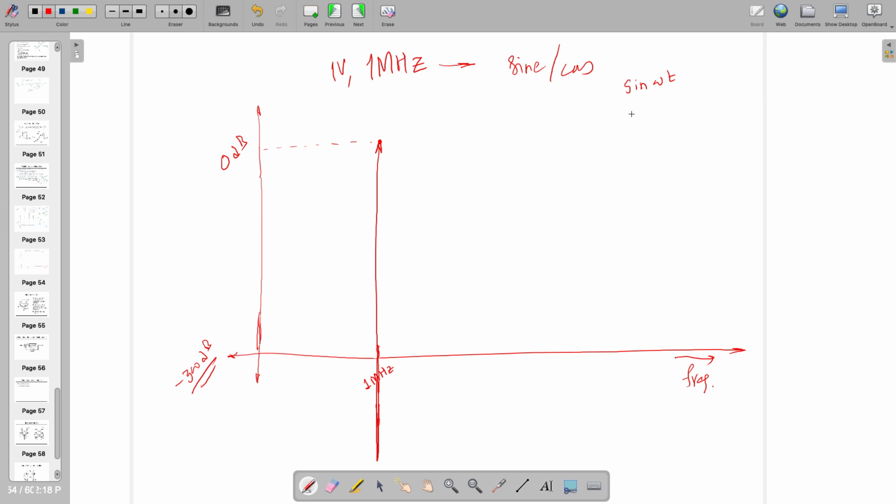No, we are not passing anything. This is just a sine wave. We are checking here. It's an independent source. Why noise? It's an independent source. You are simulating, so you are expecting 0. So everything has to be at minus infinity dB. But as Cadence has a limitation, it cannot show something like minus infinity dB. The noise given by Cadence will be at minus 300 dB as well. So you are going to see the following things.